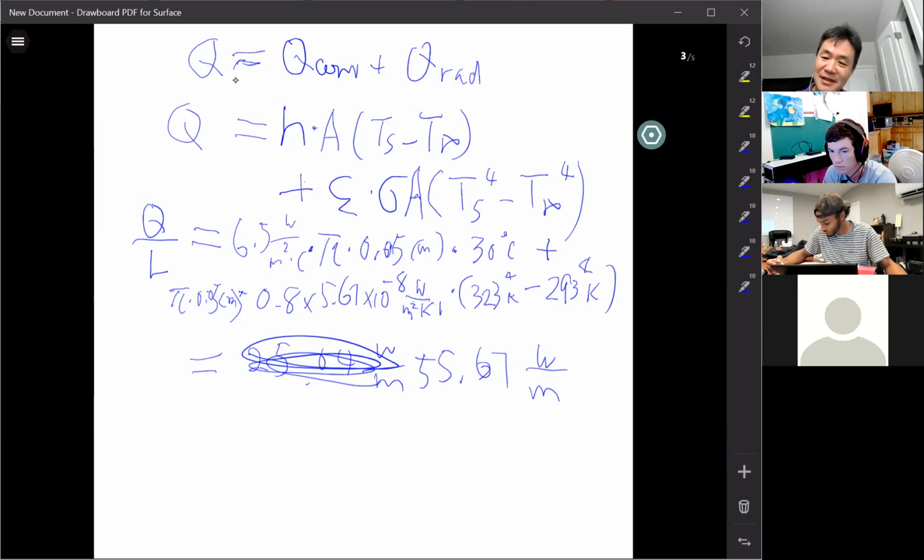We had exactly that problem in class, an example problem for the cylindrical coordinate, remember? You have to set the conduction Q equal to the convection Q. Based on that equation, you should be able to find the one unknown, right? Gotcha. Because you don't have the temperature on the surface. I think this is a hint for you.